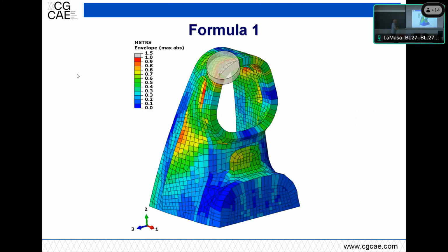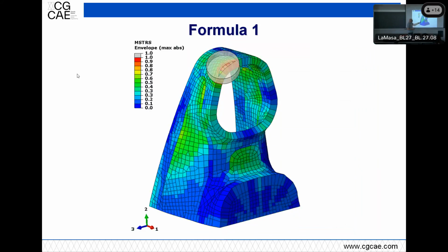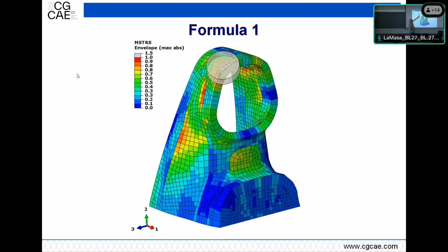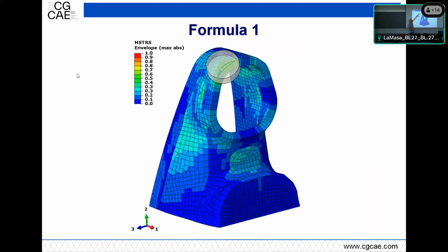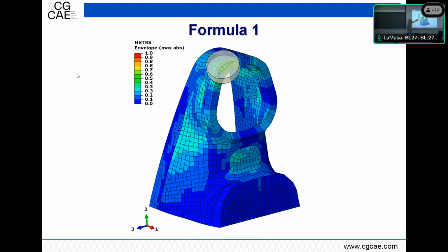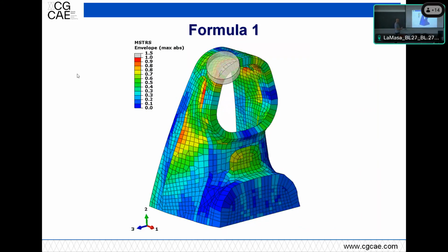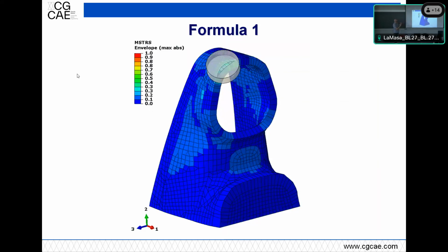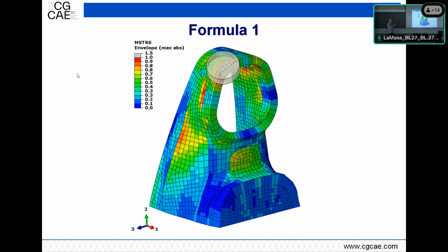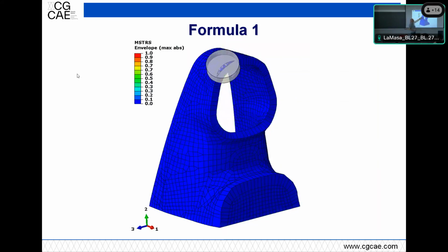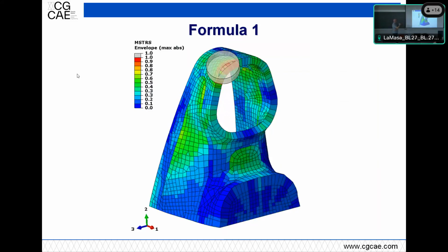we realized later, when additional computational time and elements were available, it's shown here, where we reach more than 1.5, the same kind of failure index. This was done using a 3D element. It's only one in the thickness, but each of these elements can get the description of the laminate as if it was a shell element, like the one before, so a plate element. But this can reproduce in a better way the geometry, so the high curvature there.